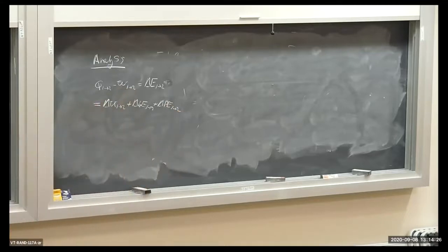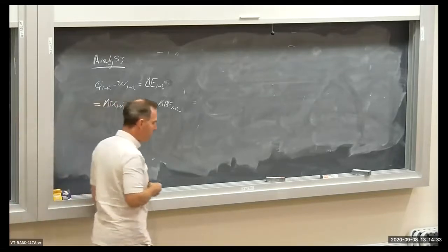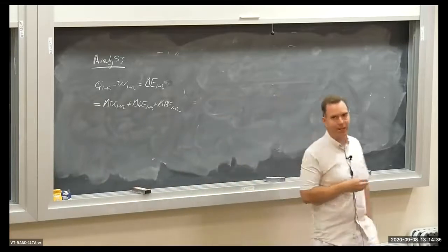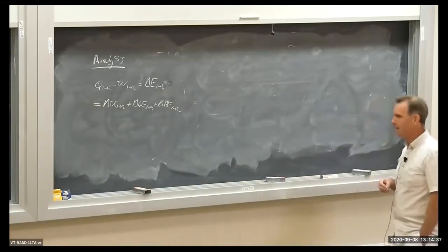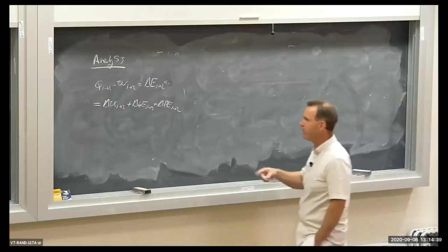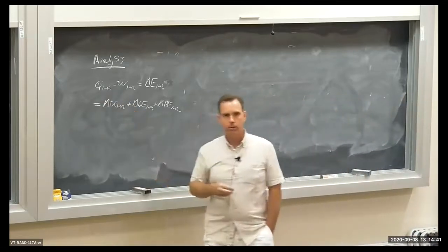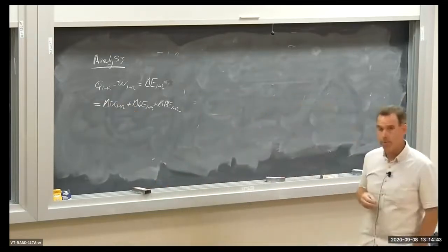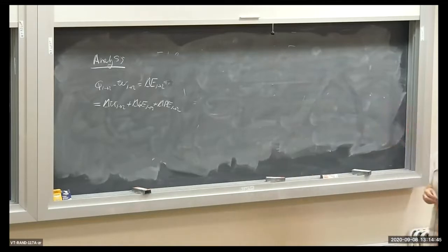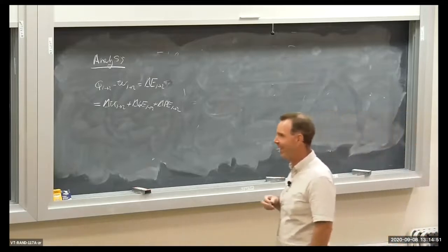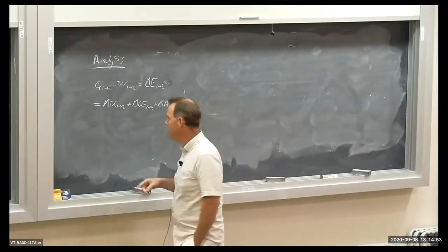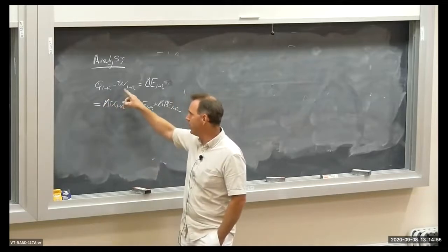Change in internal energy, potential, and kinetic energy from state 1 to state 2. Okay, let's whittle some of these terms down and see if we can get rid of some stuff. Notice that we're supposed to find the heat transfer to or from, maybe Q 1 to 2 will be negative, the air. So this is what we're supposed to find, so let's attack this term.